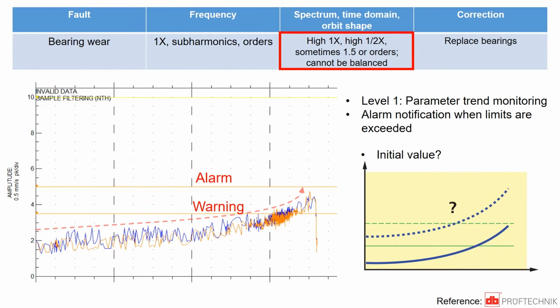Typically, if you look at the vibration measurements at the machine below, vibration tends to trend upward over time. If the large vibration is due to bearing wear, typically it cannot be fixed by balancing. So it is important to monitor the vibration over time and make sure that the machine does not catastrophically fail.